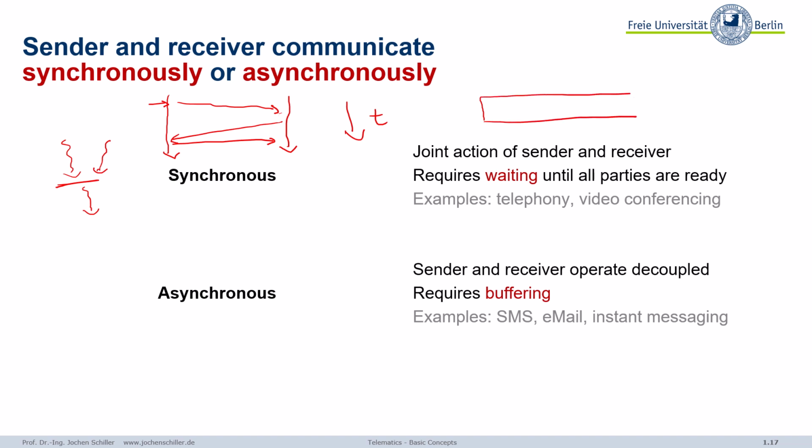There we will see we send bits, and maybe part of the bits is for the communication from A to B over a certain wire, and then follows communication from some C to D, and then maybe, just to make it simple, it follows again A to B. So this is also synchronous communication because all the senders and receivers have to know exactly the time when A is allowed to send to B, when C is allowed to send to D, etc. So they are synchronized in time, and we will see how this is used in classical telecommunication systems.